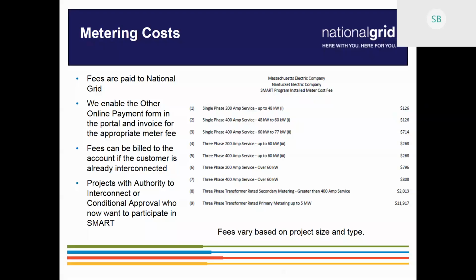So they had to specifically set the inverter PSCAD model up so that we could change those settings in order to do the PSCAD model showing that we're going to regulate voltage and frequency on this test site, only on this test site. But they needed to know that so that we would be able to configure that model for the studies that we needed to do. So that's something to consider for folks that are owning sites. That is a phase 3 solar learning I'd like to share.